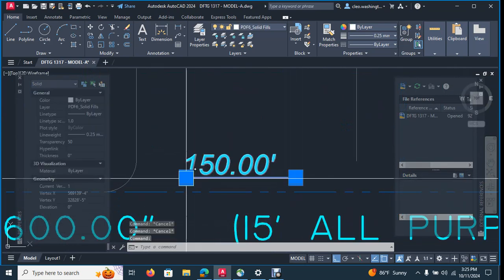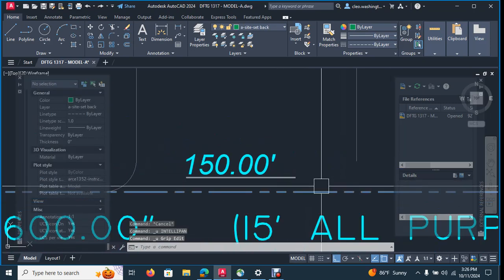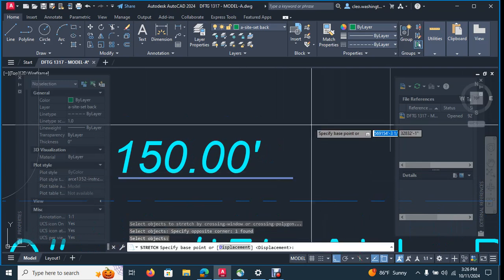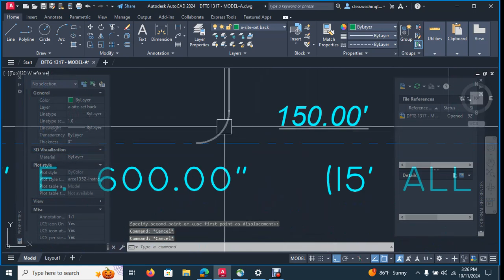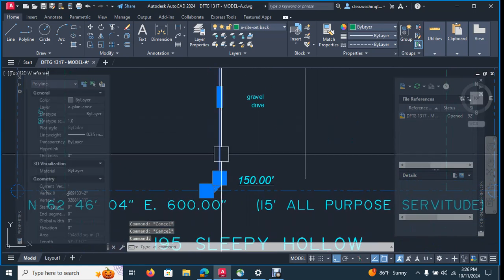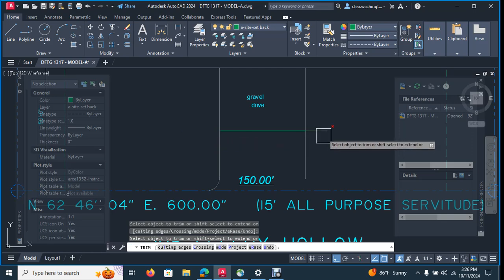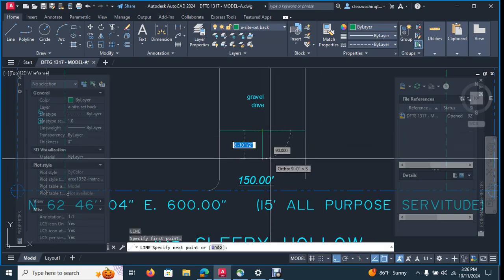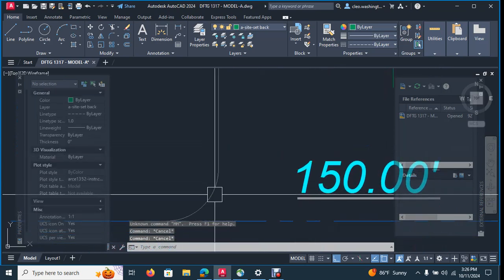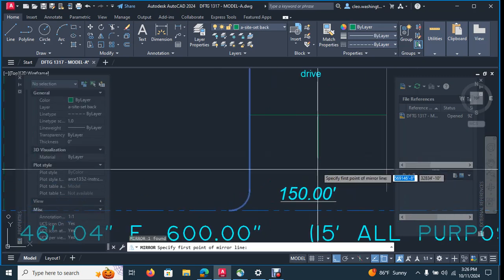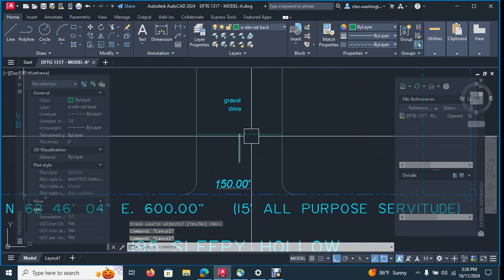Let's see. Oops, hit Control Z. Just stretch this over, make sure it's in alignment with the hyphen here. Yeah. And got to mirror this guy again. Let's see, draw a line across so we can get the correct center point. Trim it. Then draw a line southward. Then select it and hit MI, and hit enter. And then delete this.